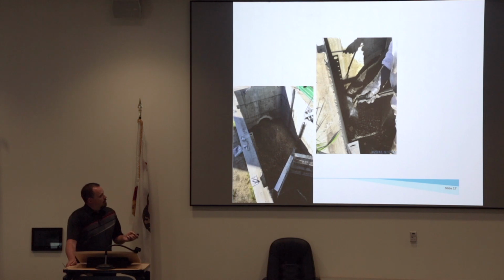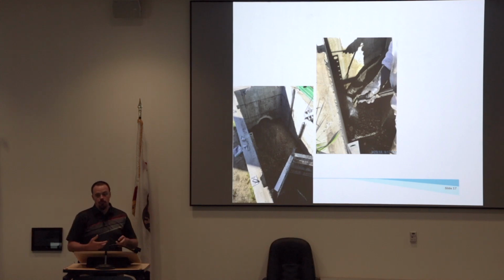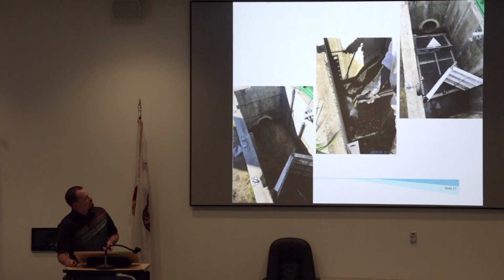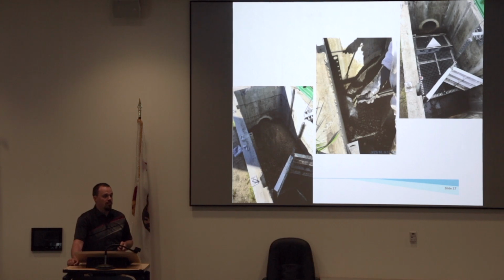When we're doing maintenance of it, we have a Vector truck, and lots of times the sediment's dried out or compacted in there so that we have to use pressure washing just to break it up so it can actually be vectored up. And then at the end we have our vault. The one thing I do want to identify here is in the vaults we have these deflectors, so right when the water comes through it disperses it and allows sediment to settle and minimizes some of the force of the water coming through this unit. But even in here, it's an 18-inch pipe, and if you watch this during a rain event, it really just flies through there. It's amazing the force that the water from an 18-inch pipe has.